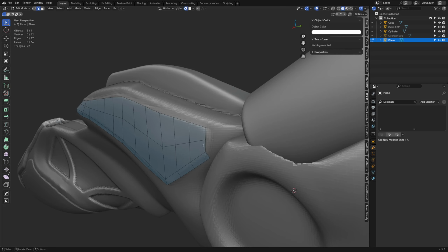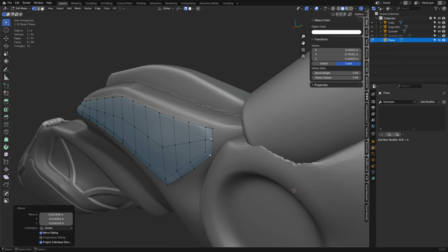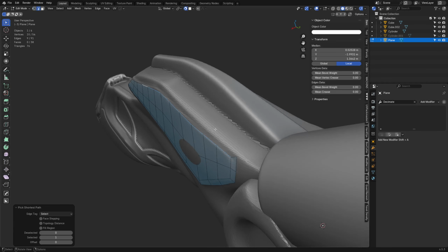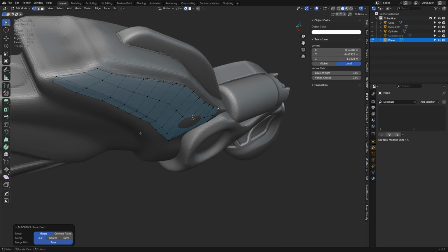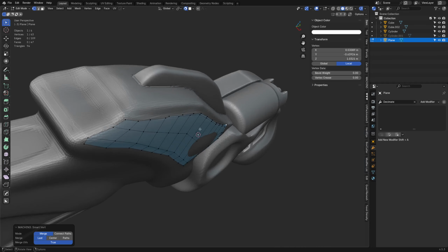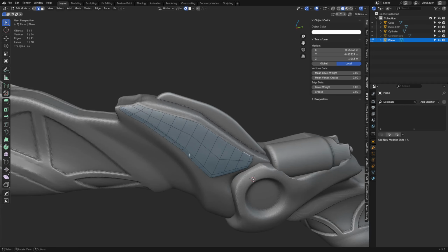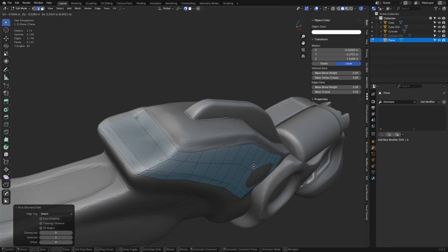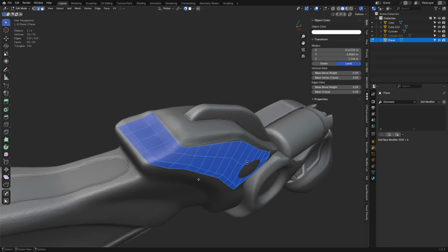In ZBrush, guys take this kind of mesh probably and will ZRemesh it if possible. Some guys still manually retopo it, but a lot of guys will ZRemesh it and move forward with it. And you want to exaggerate your shape sometimes a little bit, because you can always adjust depth and stuff later on. Here, this is very narrow, so I don't know if that was a good call to keep it. But yeah, exaggeration can go a long way. But you're going to retopo, you're going to create these kinds of quad meshes, anyways. This is going to be closer to your final results.